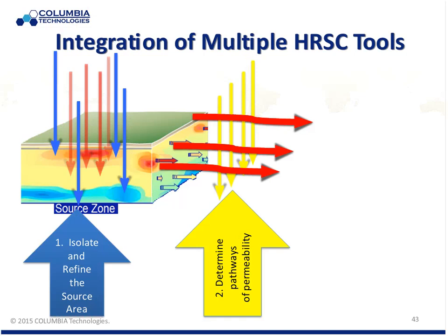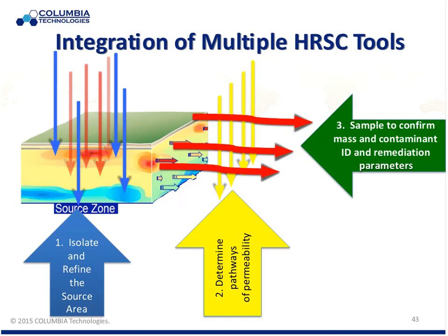We're going to try to look across a continuum of a transect at very high resolution for both the contaminant and the soil structure, so we can identify these highways of transport, and then we can go in and target the sampling, target the well construction, screen intervals, heights, and locations, and then target any remedial activity that's going to go on. If we're worried about cutting off the mass flow, we're going to try to identify those very distinct 10% holes in that vertical gradient. And that gives us our discrete samples, and we can confirm what the high-resolution tools are telling us.